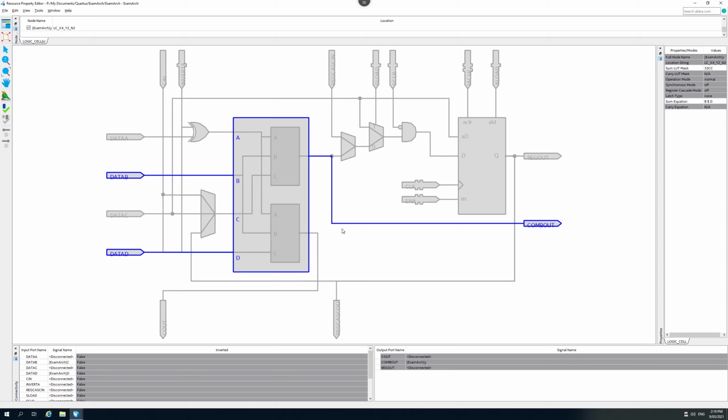So they can add faster than if they didn't have this additional circuitry here. We don't need to worry about that. We just need to understand that inside FPGAs, you've got your logic elements, and each logic element contains a lookup table and a flip-flop. And remember, all digital logic is made using either lookup tables or flip-flops.